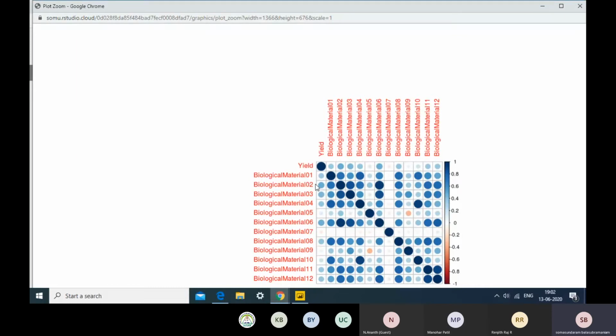So if these two things are there, probably I have to select any one of them, and I have to select a variable which makes more sense for the process. Probably I will select, say, the viscosity, if that is important for the process, or that is what the operator can control. Or some places people will say, I cannot control the viscosity, but I have a chiller or some equipment which can alter the temperature. Then I will leave viscosity and take temperature as one of the variables for predicting the yield. So this particular call you have to make in consultation with the subject matter expert or your process engineers, because they only can tell you which particular parameter you can control.